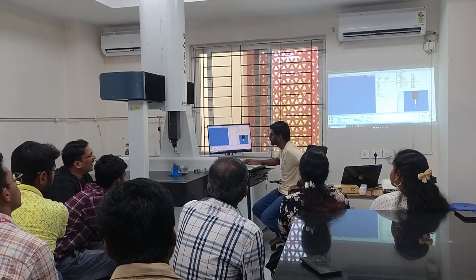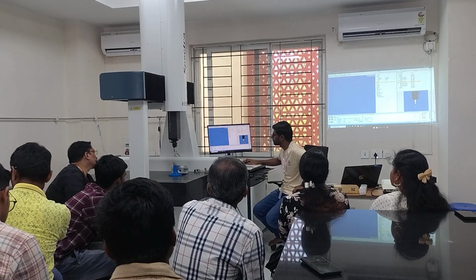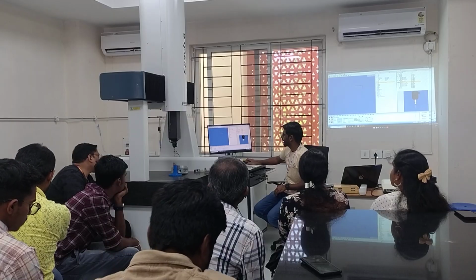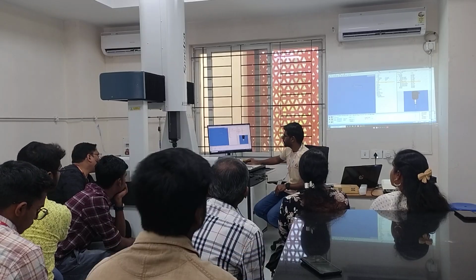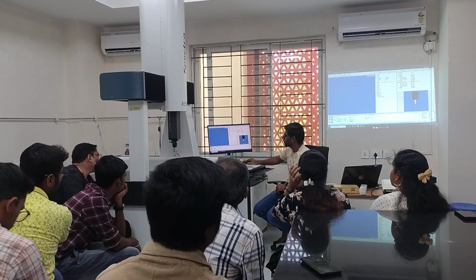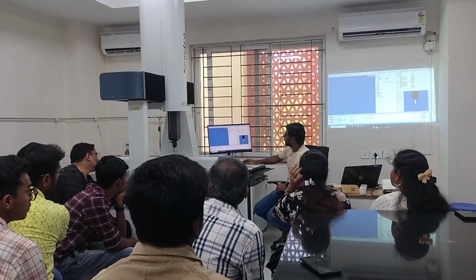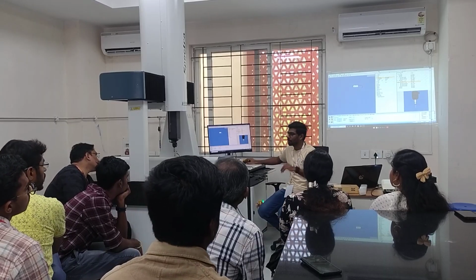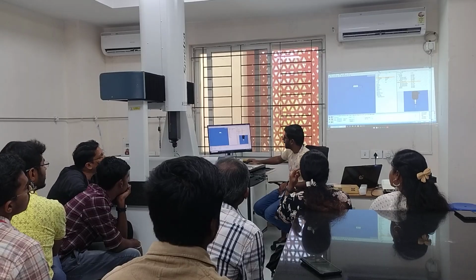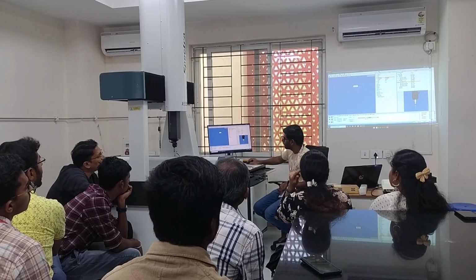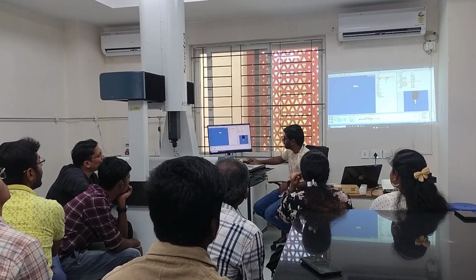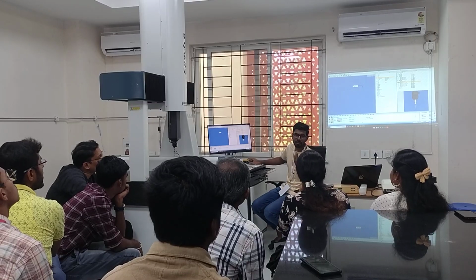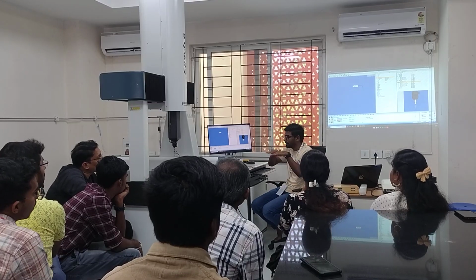This is the distance. I'll measure the distance between them. Let us go first for the flatness. Okay, I'll click on flatness. So which plane flatness do I want to have? I take the top plane, actual one, not the nominal. Nominal always will have the perfectly flat part. So I'll take the actual and I will drop it in the plane. For flatness, is there any reference required? No, because it will be comparing all the points with itself.